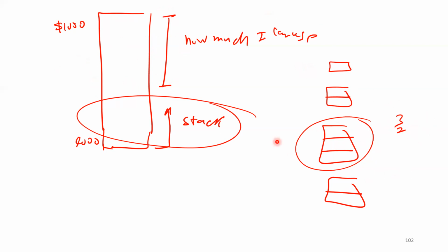And again, we are gonna start our data from 1,000. We are gonna start our stack from 4,000. I'm telling you, this is hardware. The hardware does not understand. If you start from here and you say push, the hardware is gonna write, so maybe you are gonna go to your variables, your arrays. You are gonna write some data there. Okay. So for sure, your program will crash if you do that. So you have to make sure.